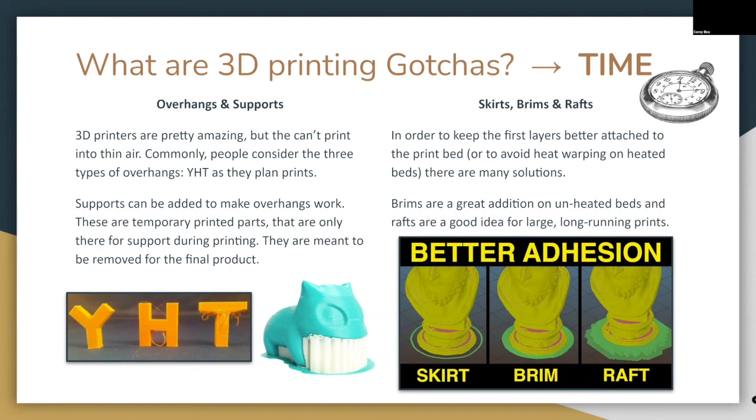A Y overhang, you've got a central spire and then they sort of fan out from that center, like the top parts of the Y. Those are usually not that big of a problem because the rows above, even though they're sort of extended, are also like 50% over top of something. There's some angle where if you're within that angle, it won't collapse. And so usually 40 or 50 degrees is a good marker for how much you can stretch it.